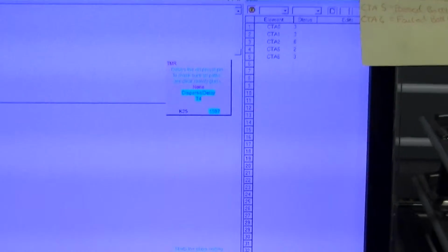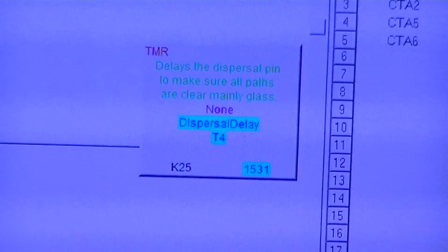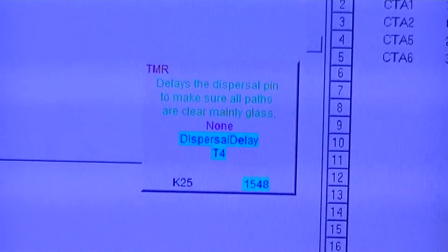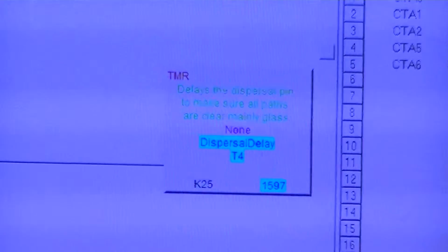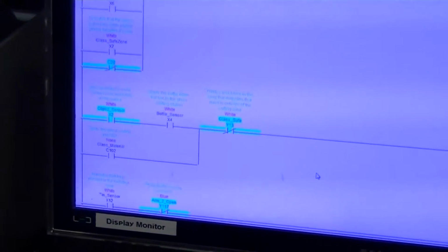And moving down, we have a delay timer, so that when the bottles actually come through, they get laid down so they're in front of a sensor for a period of time, and nothing can run through at the same time. So what happens if we don't have that delay in there, it'll send items down, but it won't distribute them down their correct path. So we had to put a timer in there to wait 2 seconds if a bottle gets done before it sends down anything else.